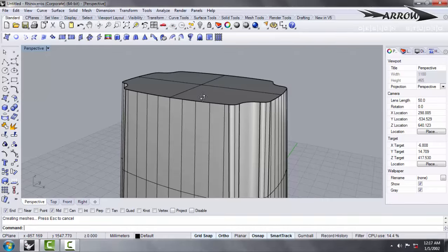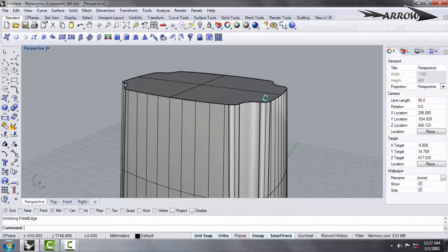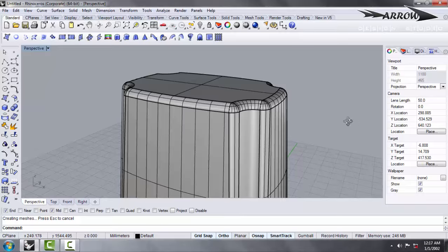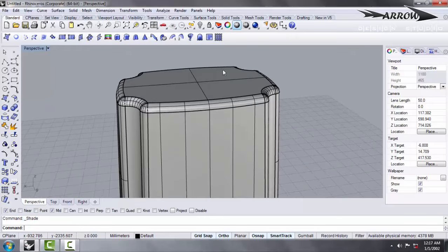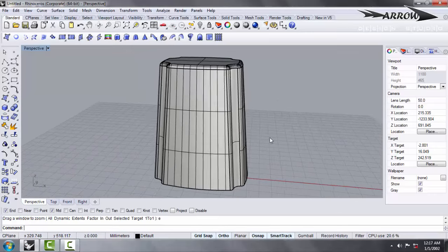Okay, now I also want to give fillets on the top this way, fillet edge, but now I'll say 15 and I'll select the top edges and say enter. I'll just see whether it happens, but it does not happen. So I'll tell you one technique. Whatever fillet you are giving over here, the fillet should be at least 1 mm less than the fillet that you have given. So it would happen, even though it is not happening prior to giving. So now it has taken place, you can see.